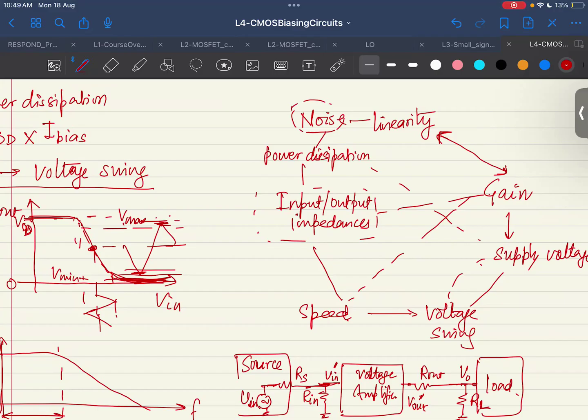But we see that it is something to be dealt with, or kept in mind when you are designing analog circuits. And one way to really counter noise, other than the differential we saw in the amplifier, is when you keep the voltage strength of your signals quite high, that means they would be much higher than the noise floor which you have, because noise is small.